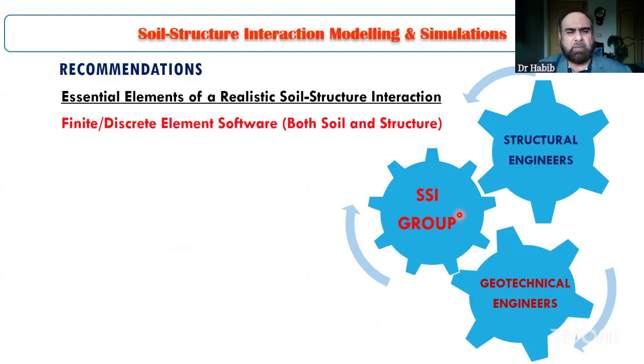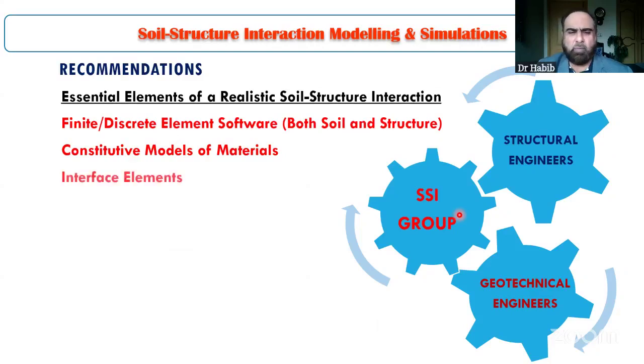First of all, there should be a finite element based or discrete element based software which can model both soil and structure, not only soil or only structure. Second, constitutive modeling, or input of constitutive models of materials, for concrete, soil, rocks, whatever materials. And the most important part is interface elements, or interfacing of these two big regimes. That is very important because if the interface modeling